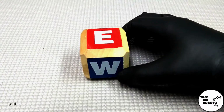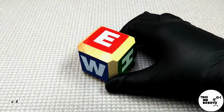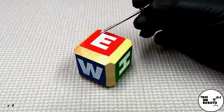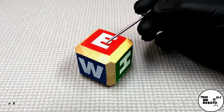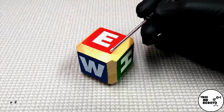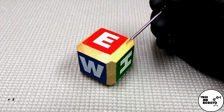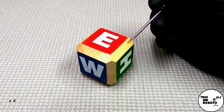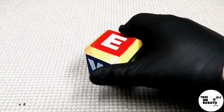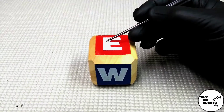If your workstation moves a little bit, rather than reteaching all of these motions, you can just reteach this one coordinate system. So you would set this as the origin. Now you would set this as your X, and you would set this as your Y. So before, your robot did a path like this, right?